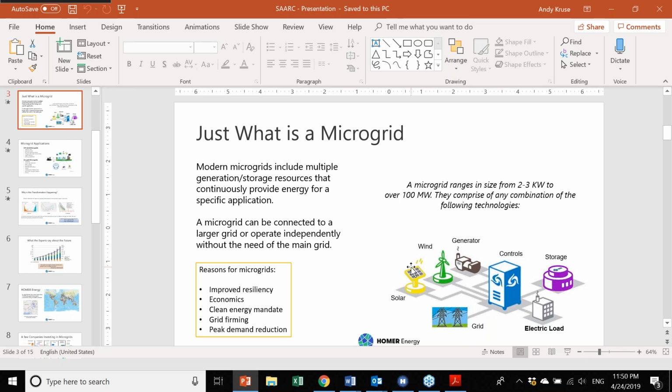When you are looking at those designs, it's important that these technologies have some kind of certification provided to them, usually by an independent laboratory. It has to be like an IEC certification or a UL certification based in the United States, or a CSA if it's in Canada. These are specific types. Some people will say they're CE certified. Well, that really isn't a certification, so it's really important to understand that.